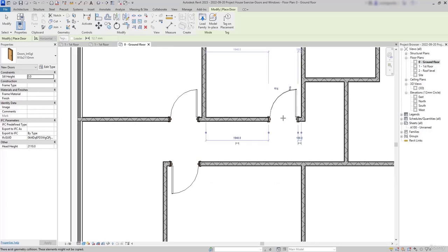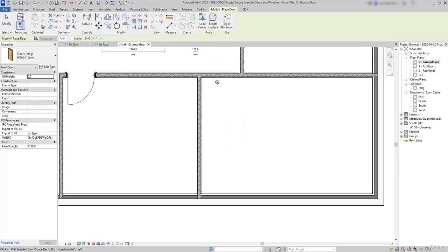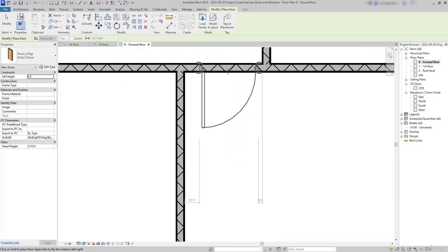Another thing you've probably noticed is that you cannot place a door alone. And honestly, I think it would be a bit weird at least. So, doors and windows are hosted by walls, meaning that they only show when you place the mouse over a wall. So now you can keep placing the doors for all the rooms, you can follow the image I shown before, or just place them in your way.